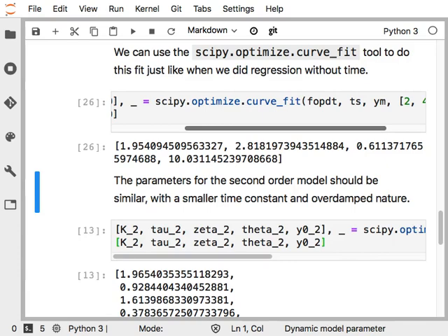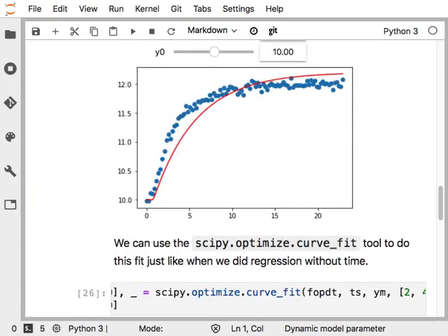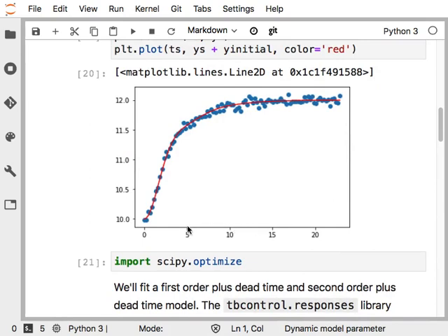And so I always recommend this kind of 1-2 process, right? Start with your eyes, get a good feel for it. Remember, you don't have to do the interact. You can also just estimate, right? So you can say, look, looking at this, if that was a unit step, clearly the gain is about 2, right? Because it's 10 minus 2, 12 minus 10. And looking at the general time scale of this response, if it's a first order response, maybe the time constant is about 4. If it's a second order response, maybe the time constant is about 2, right? You can eyeball that easily knowing these other rules, but just from a very loose version of this.